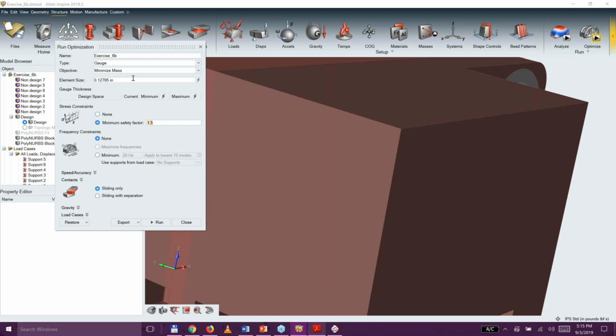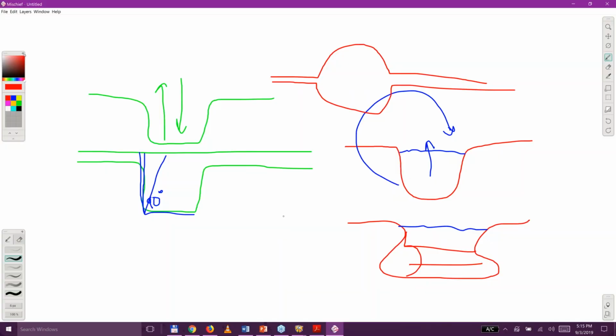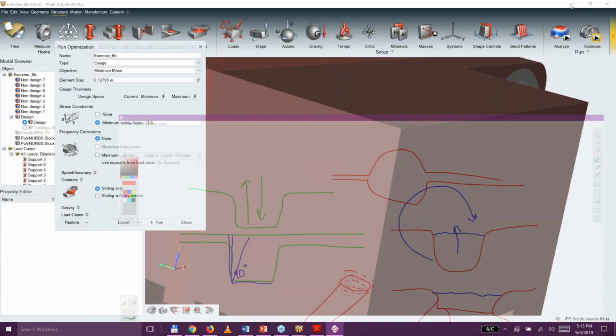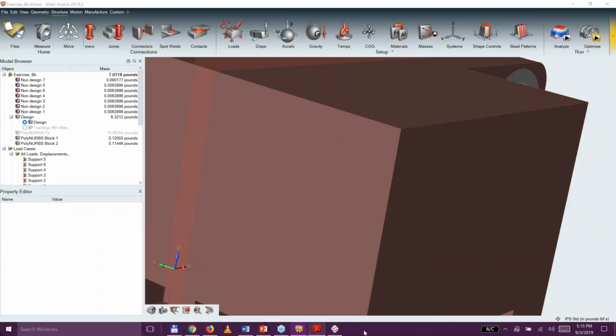And what that's going to do is calculate the ideal thickness of the surface. So you're representing a tube with just a single zero thickness surface that you apply some thickness to, and it will optimize the proposed thickness of that. But for weldments, we don't have the capacity to optimize things like that.